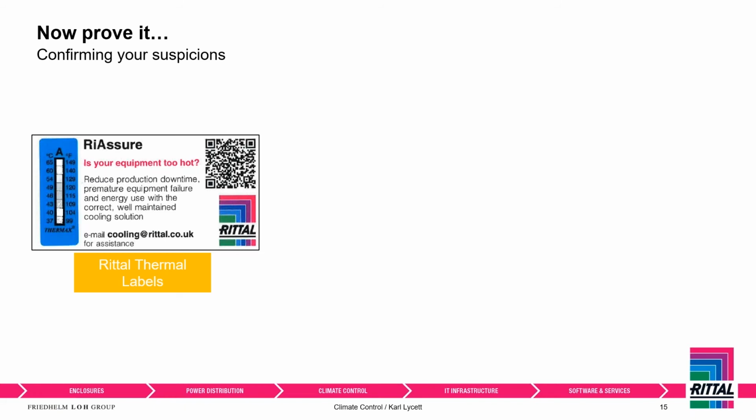So these guys, you stick them on the inside of your enclosure, on the door, preferably on the inside, guys, not on the outside. We have seen people use them wrong. Stick them on the inside, and what happens is those little squares on the blue strip on the left-hand side, if they see that temperature, which starts at 37 degrees Celsius, they will black out, they will sort of blow out because there's chemicals in there, and they will stay blacked out forever.